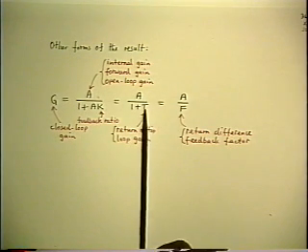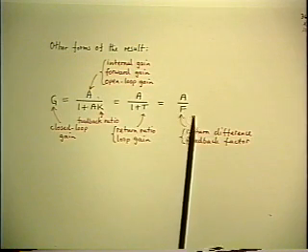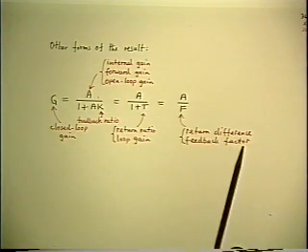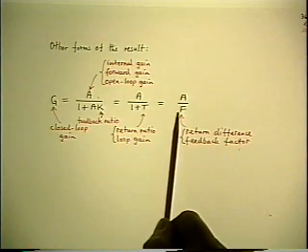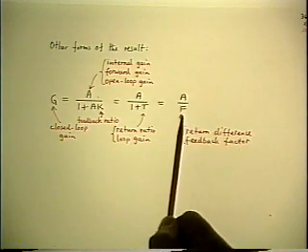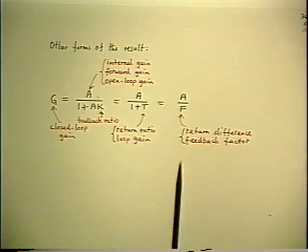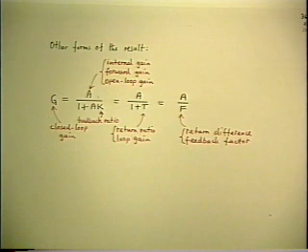1 plus T comes up so often that it also has a symbol of its own, F. I like to call it the feedback factor, because it's the factor by which the open loop gain is reduced in order to give you the closed loop gain. In other words, it's a measure of how much feedback you have.